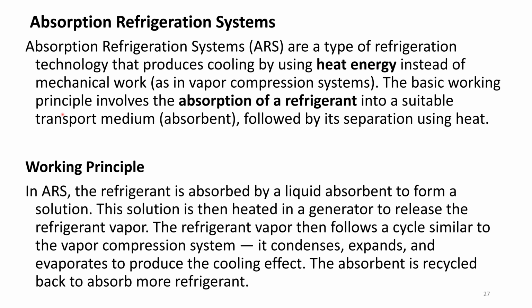So now it's time for discussing another refrigeration system, that is the vapor absorption refrigeration system, that is ARS or VARS, a type of refrigeration technology that produces cooling by using heat energy instead of mechanical work, as in the vapor compression system. The basic working principle involves the absorption of refrigerant into a suitable transport medium followed by its separation using heat.